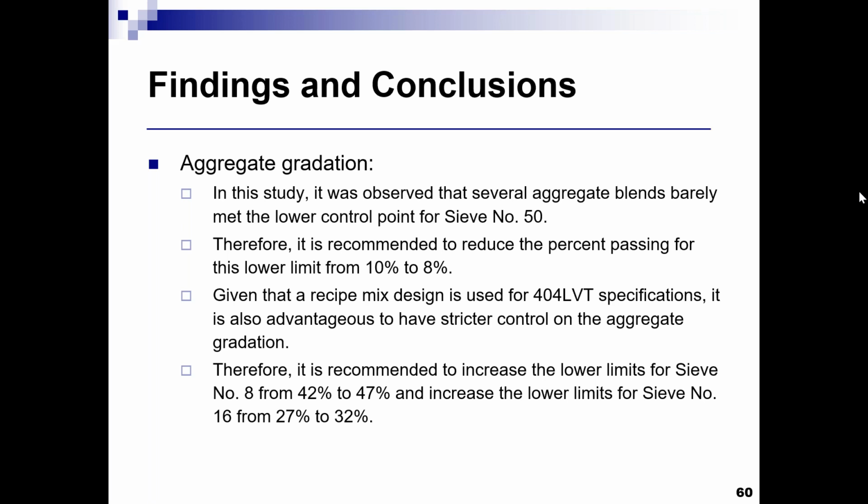Is the use for this mix for rural sections, or can it be used in small residential subdivisions that are curbed/uncurbed? It really depends on the conditions at the location where you want to use it. If you have a relatively flat surface where you can easily pave it and control the thickness to be the desired thickness, and you have a good foundation for this mix, then it can.